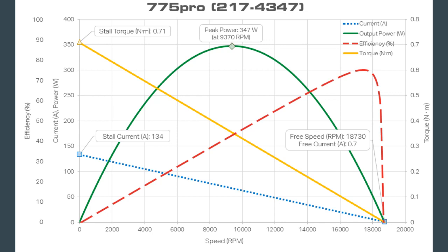And the higher your current draw above 40 amps, the faster it's going to pop. So if you're at 130 for like a second, it's going to pop. And when it pops, does it permanently break the breaker? No. There's a difference between a fuse and a breaker. A breaker just disconnects, then pops back after about a second. Sometimes you'll hear this popping sound with the breakers. That's the breaker popping back and forth.